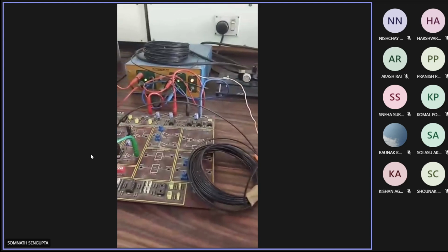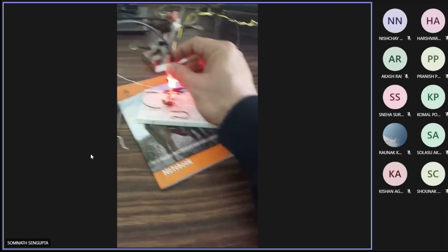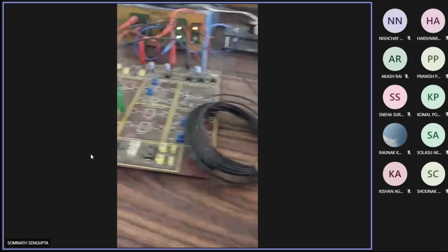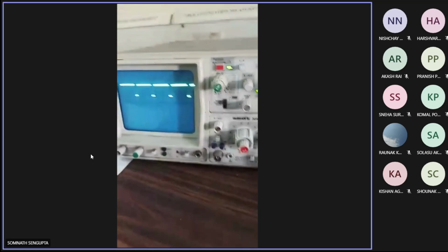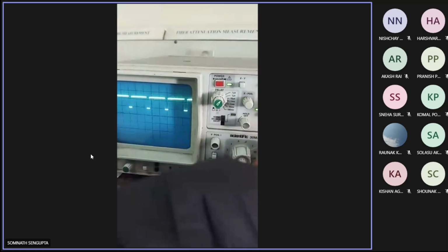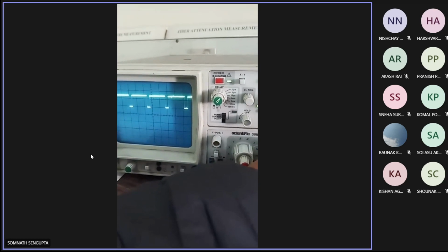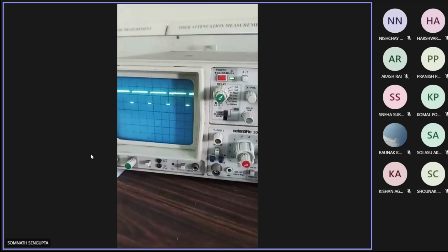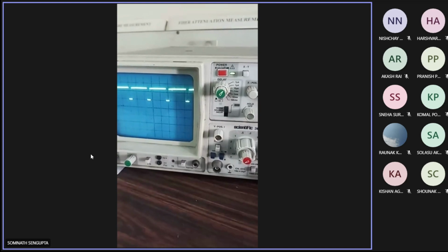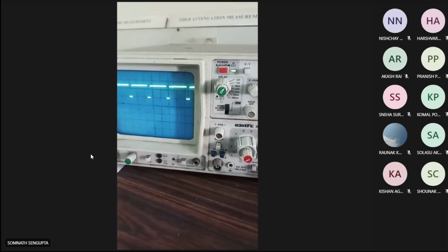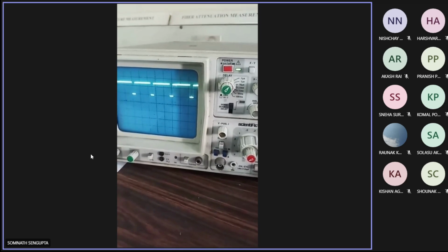So it is of 10 meters. Directly you have applied the light on the fiber end, and one end is connected to the detector. Okay, and you now see the output voltage. Now it is decreased, decreased a lot. It was an exponential decrease because that was 0.5 meter and now it is 10 meters, so it is 20 times increased length. Okay, and you note down the voltage.